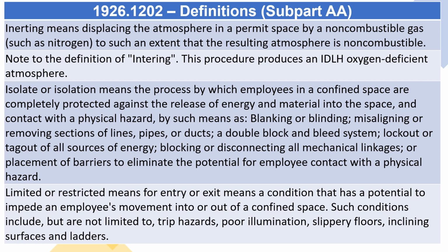Isolate or isolation means the process by which employees in a confined space are completely protected against the release of energy and material into the space, and contact with a physical hazard, by such means as blanking or blinding, misaligning or removing sections of lines, pipes, or ducts, a double block and bleed system, lockout or tagout of all sources of energy, blocking or disconnecting all mechanical linkages, or placement of barriers to eliminate the potential for employee contact with